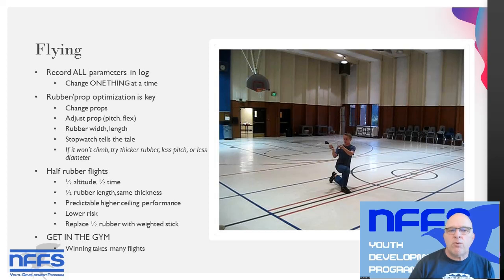If the plane won't climb at your highest torques, try thicker rubber, try less pitch on the propeller to get more power to get it spinning faster, or less diameter on the propeller.